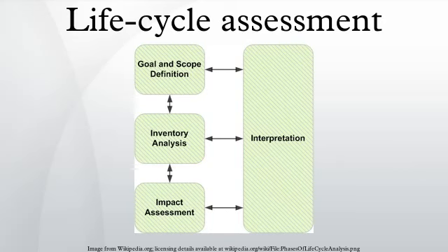Second, a single measure of stress should be selected. Typical LCA outputs include resource consumption, energy consumption, water consumption, emission of CO2, toxic residues and so on. One of these outputs is used as the main factor to measure and streamline LCA. Energy consumption and CO2 emission are often regarded as practical indicators. Last, the stress selected in Step 2 is used as standard to assess each phase of life separately and identify the most damaging phase.